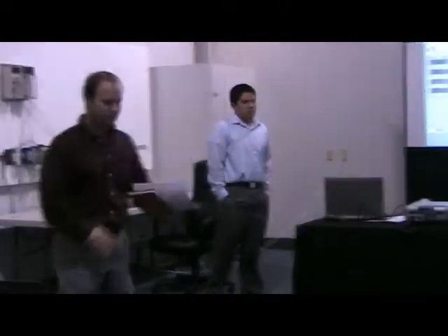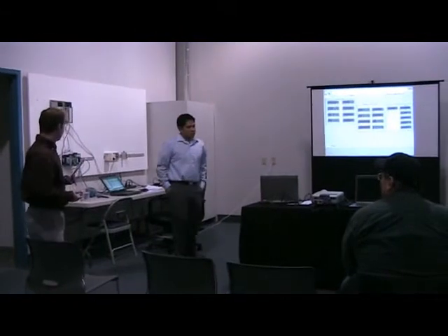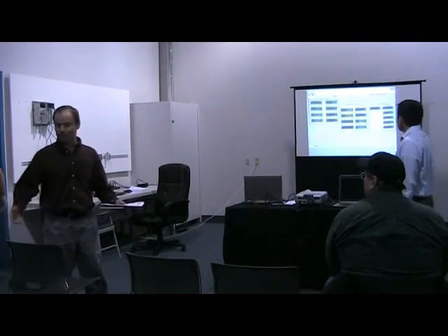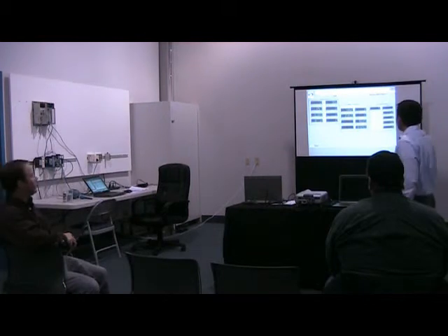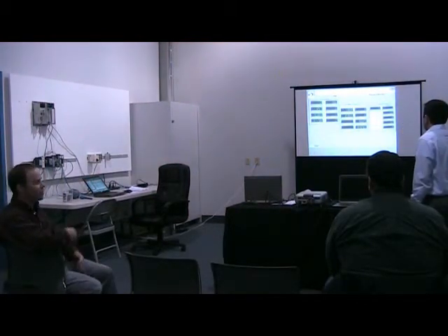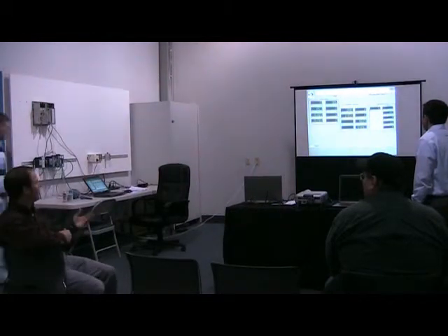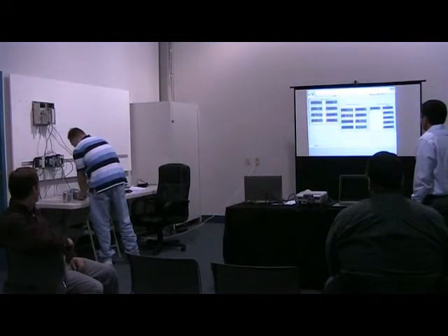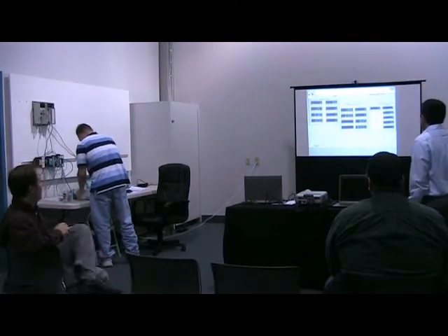Simply put, we threw together a little SCADA screen. Instead of showing all the motors and pumps, we just showed general data for one instrument. We picked a temperature transmitter, a simple, very rudimentary device, just to grab some HART data off of it and show you some other data we could get. Just general information. There's a variety of stuff you can gather. We just cherry pick some items to put on the SCADA screen. He's going to throw that temperature module on ice to see that we are reading real data on the analog and HART data.